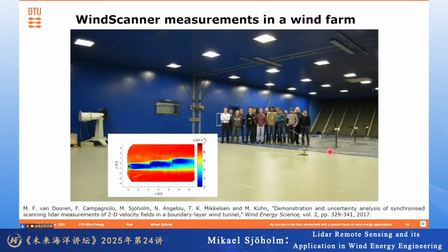And the purpose in this experiment was actually to study a small wind farm, three wind turbines, how you can steer the wakes and how that could be used to optimize the whole wind farm energy output. Here you see a measurement of these three wakes when they are almost aligned with each other. Yes, and the wind direction is of course very fixed in a wind tunnel. So what we have to do here is place the wind turbines on a big rotating plate that could be rotated to illustrate different incoming wind directions.